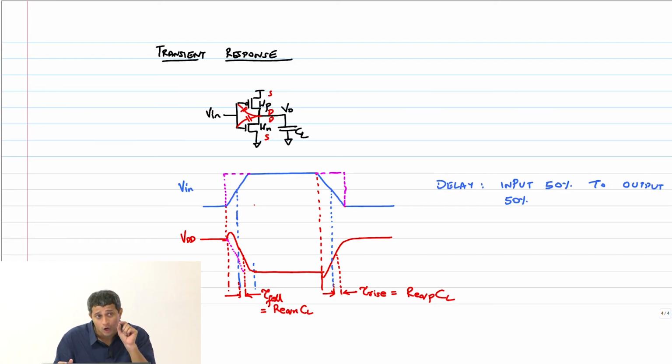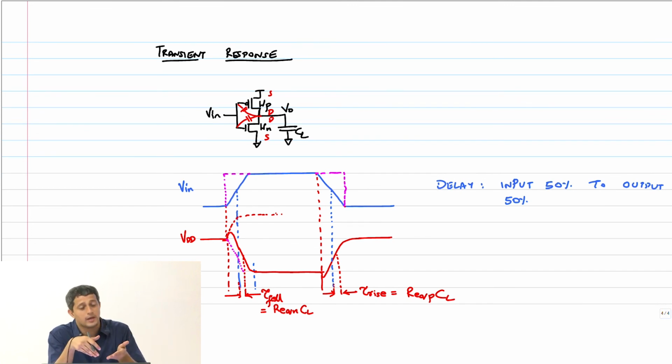However, if the NMOS did not turn on, then this node voltage would jump to a much higher value, and it would actually remain there after that. It can remain at a value much higher than VDD, because nothing is there to pull it down. This is what I meant when it's called a floating node. I'll come to this later. You will see this happen in your simulations also.